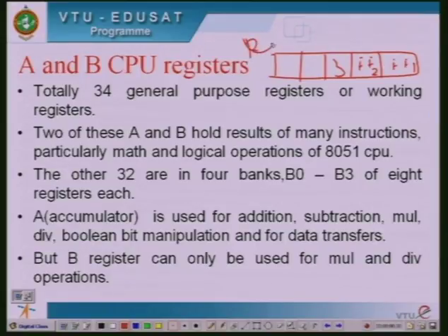This is called a register, and this register will be either 4 bits in length or 8 bits, and in our microcontroller 8051, almost all the registers are of 8-bit length. Every register will be of 8-bit length in our current microcontroller. So please remember, a register is nothing but a collection of flip-flops where data can be stored.